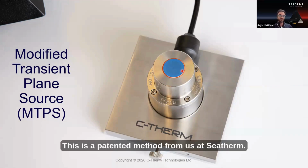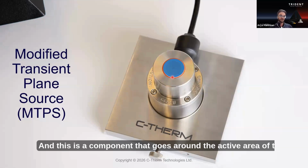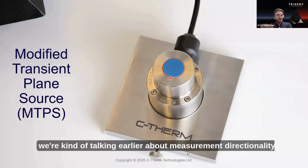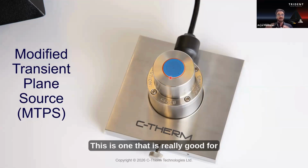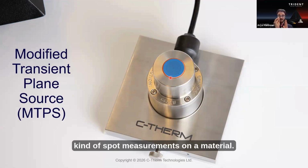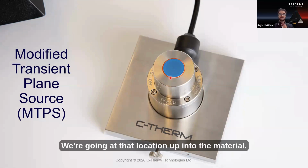With the MTPS, this is a patented method from us at C-Therm, and one of the reasons for that is related to the guarding, and this is a component that goes around the active area of the sensor. What it effectively does is help promote a one-dimensional heat transfer into your sample. So when we were talking earlier about measurement directionality, this is one that is really good for assessing localized spot measurements on a material, because wherever you're placing that sensor, you can view that direct spot as what is being assessed. We're not measuring outwards. We're going at that location up into the material.